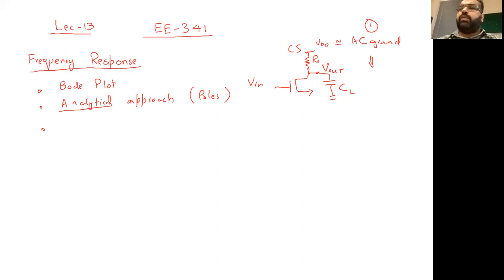And then we said, okay, we talk about those capacitances which are between one node and the ground. But what about this configuration, when we have something in the middle, a floating node that's not connected to ground? Then we saw a powerful concept, the Miller capacitance. We saw the Miller effect or Miller theorem, how we can separate this one, the green one, which is CF, into two independent capacitances, one from this node to C in and one from here to C out. We also have seen this in the last lecture.